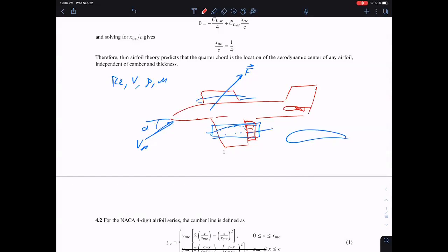And early on we decided, well, we're going to cut it up. We're going to neglect the fuselage for now and assume that the major forces are coming from the wings. And the way we can analyze at least the main wing, or any of the individual wings really, is to cut it up like this and look at the airfoil. What's the aerodynamics happening on the airfoil, right? So on this airfoil, we're going to have some total force, and also a pitching moment. We use a little m for that.